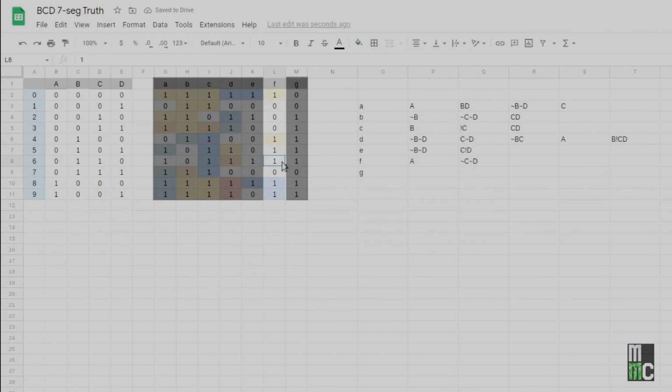Now we also have several other gates that we have options for here as well. We can check out our B, not C situation, which is this one, B and not C. And we actually have that one taken care of. Those are the only B's and not C, so it easily gets that gate. I can't get this one at the same time because between these two gates, these three bits are all different, so I have no combination that I can do. It actually looks like it's best to, in this case, go ahead and find a way using B and D.